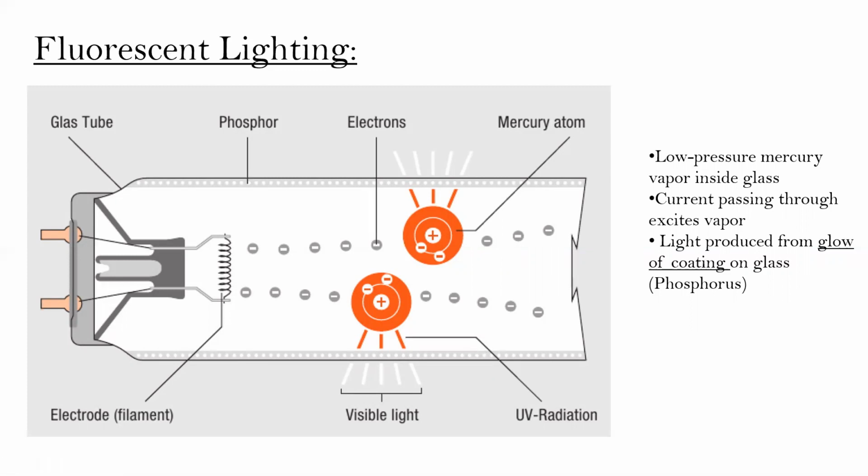Of course, one of the main detractions of fluorescent lighting is that when we are relamping a large facility where there's hundreds of lamps being replaced, they need to be disposed of properly, which means you can't just throw them in the garbage bin, because what ends up happening is we release significant quantities of vaporized mercury into the air. So there's a number of different types of devices we can use to capture that gas and to recycle the glass and the metal end caps.